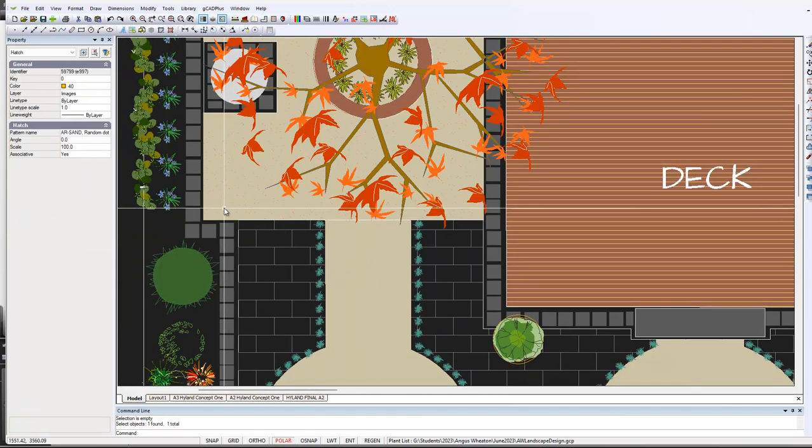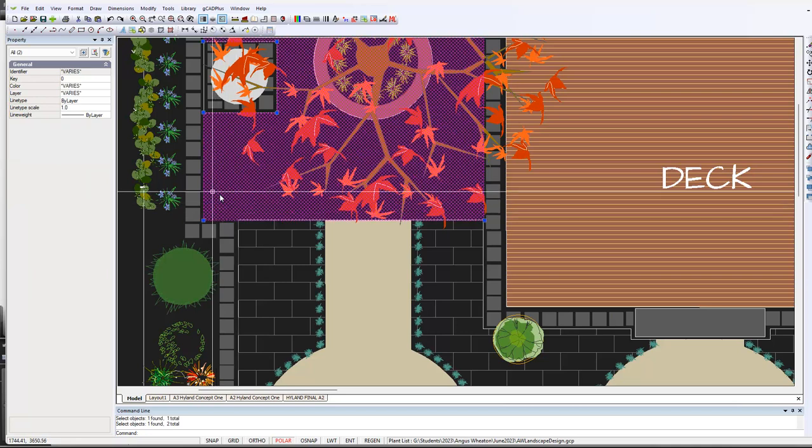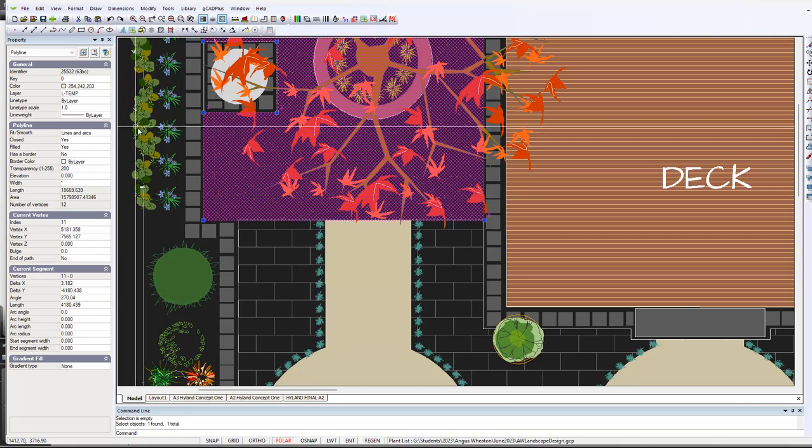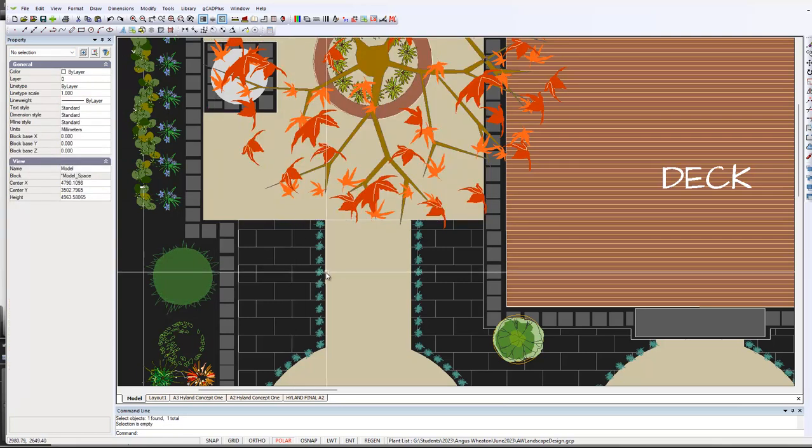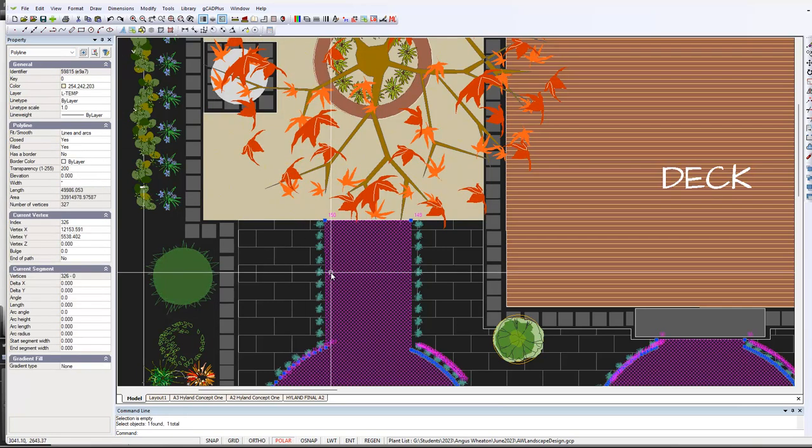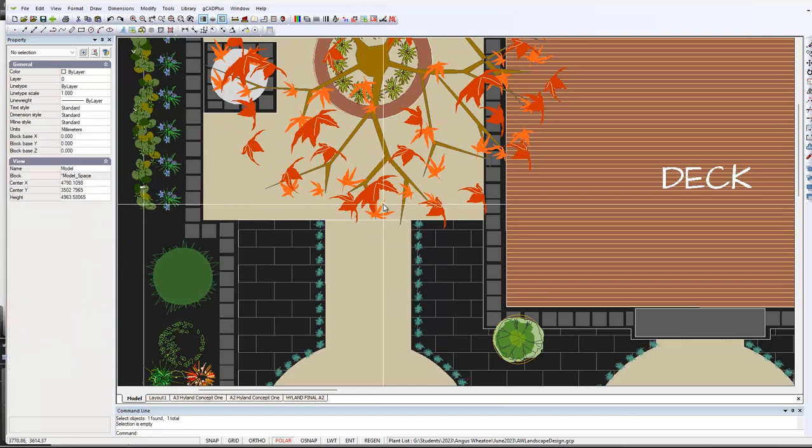And this granitic area here consists of, click that twice, a polyline, and there's another polyline here. So we have two polylines, both the same colour, both with a fill and forming that part, but we're left with that awkward line. If we try and cut it, then we'll destroy the whole polyline.